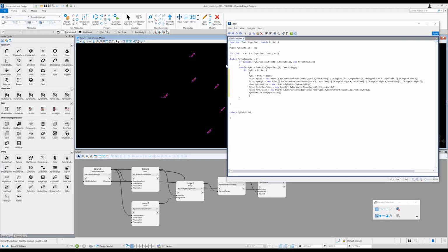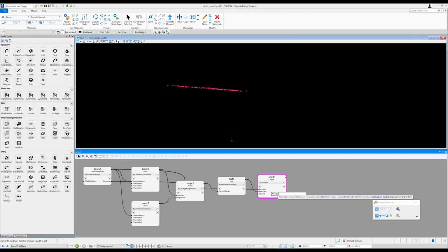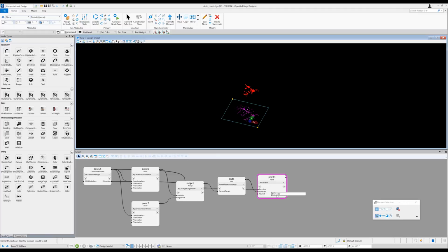So if we click apply, it will generate the RL points again, and this time the rogue points have been removed. If we change the RL limit value again to say 80, you can see the high points are included again. Similarly, if we go down to 64, we can trim off values. So let's change it back to 66, that will include all the points we need.